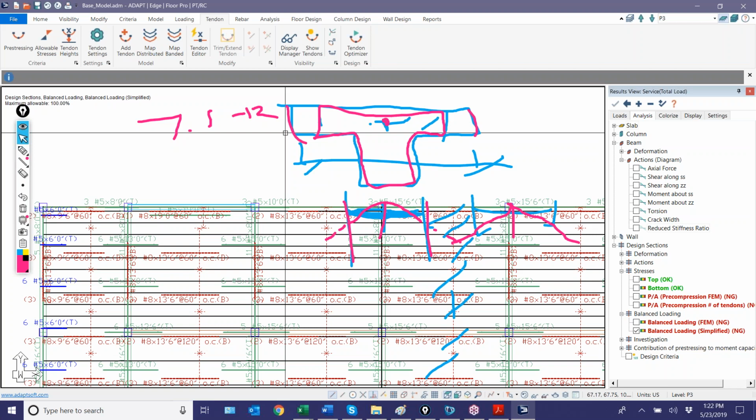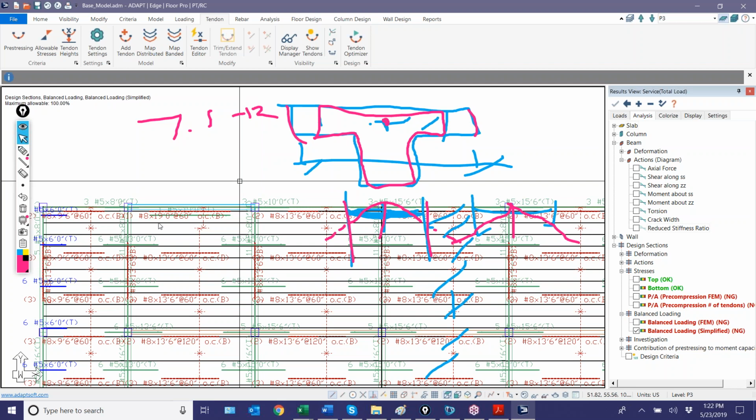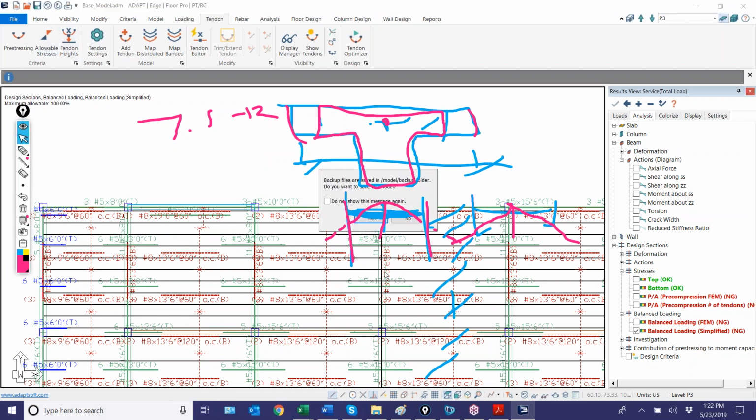You have to base the analysis on a cracked section property, which you could do in the program. You could assign multipliers to elements to simulate the cracking, where you're reducing the stiffness of the element. You also have to provide crack deflection checks and some prescriptive reinforcement in the side walls of members for a Class T design. So yes, you could do that in the program, but just be aware you have to change the target you're working with when you do that.